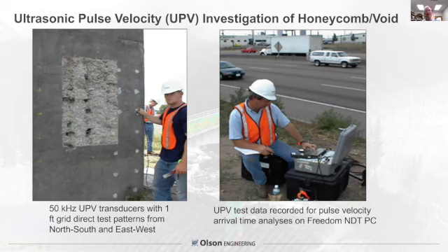Okay, another technique that we've used on bridges, in this case, it's a big bridge column. That's part of a big bridge sign, actually, on an interstate. So I shouldn't have called it a bridge. It's a column sign, a very large digital sign. But we're sending ultrasound through on a 1-foot grid because nobody consolidated the concrete. They just dumped it, and they ended up with void and honeycomb. And chipping into that surface found the void and honeycomb. So now the state DOT wanted to see if they could save the column or not.